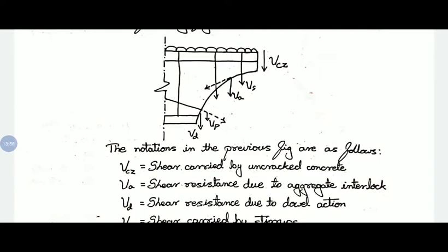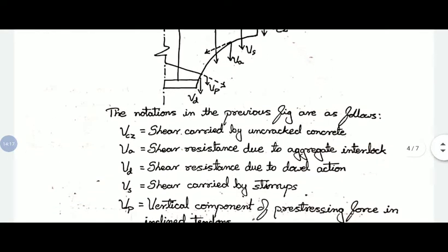And VS, shear carried by stirrups. Shear reinforcement, what we call it as. Shear reinforcement, why we provide, that is stirrups. So some shear stresses or shear forces will be carried by stirrups. Then the vertical component of pre-stressing force in the inclined tendons.